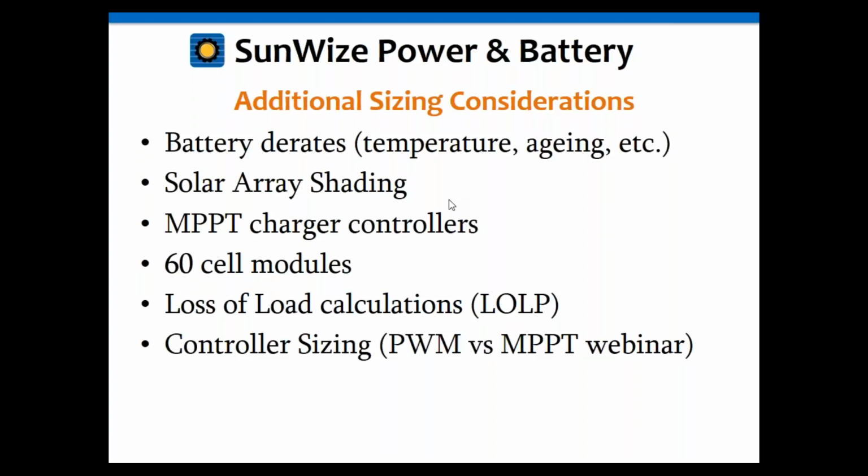But the problem is this: if you're only working with one module and you shaded one cell, there's nothing to extract, basically, because there's no current. So if you have, say, multiple modules in parallel, then it can help to do that. But if they're in series, it's the same problem because again, you've limited that current to zero. So again, it depends on what you're doing.